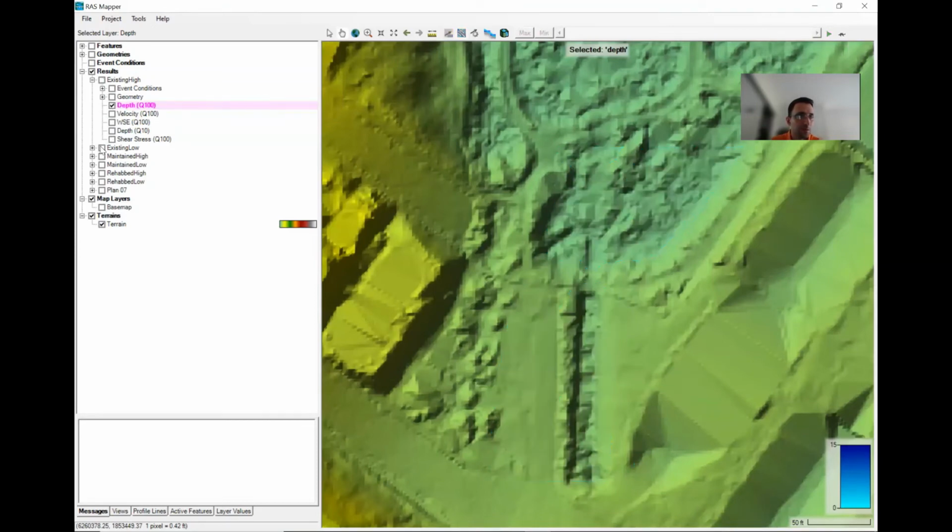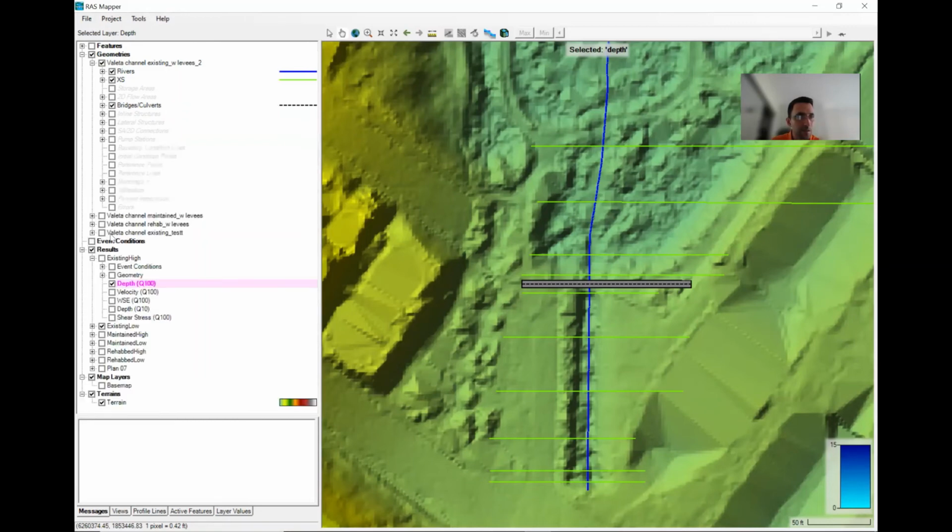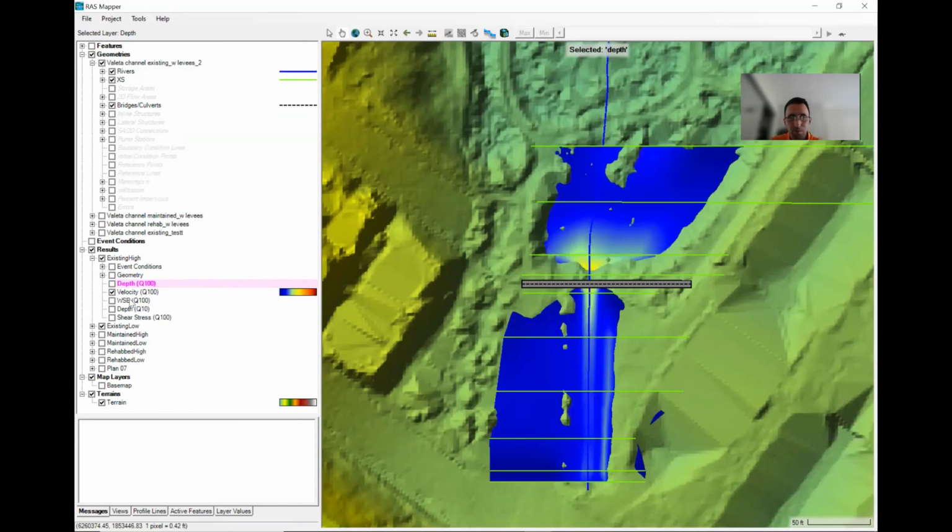just compare different scenarios if you want to do for existing. Just easily you can compare things. You can basically show also your geometry in it if you want to add your culvert. So you can see this is your road and this is your basically how velocities, for example, change. You can see very high velocities as you approach the culvert and after you leave it. This is governing the flow for this part.